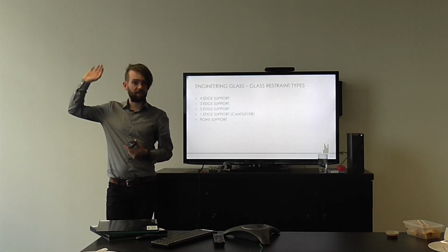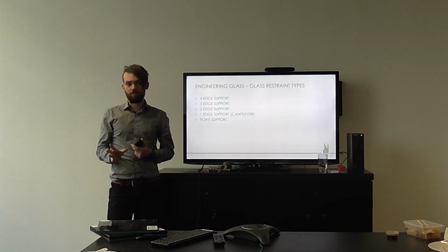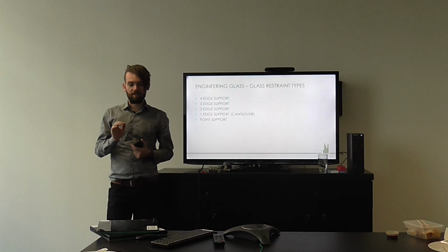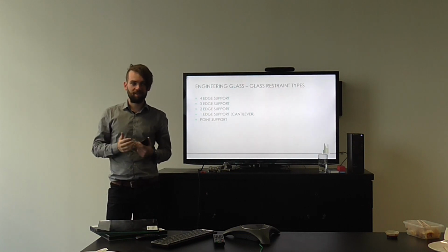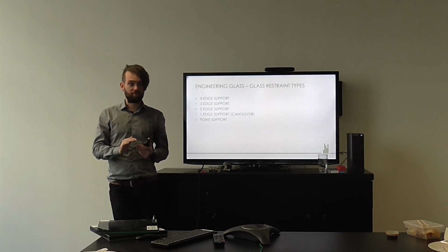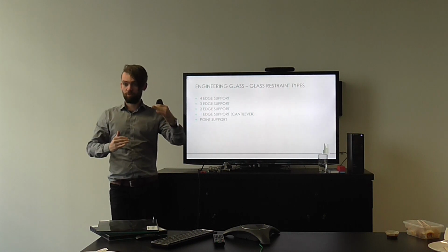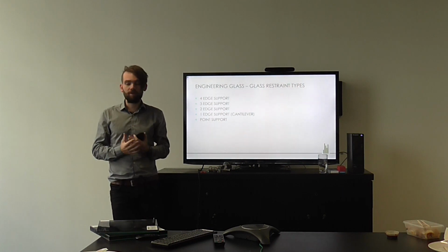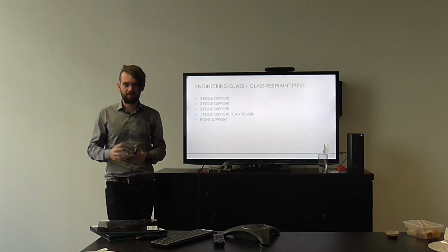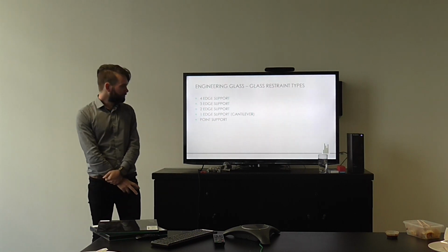monolithic toughened glass breaking and falling from a great height, in the Australian standard, the way that is actually written is that, provided that fall is greater than 5 metres, the glass needs only be heat soaked. Whereas our specification says if it's above 3 metres, you can't use it. So you're definitely right, there is a gap between what is compliance and then what we try and push, and it's just about us driving industry best practice and making sure that we're being safe and people aren't going to get hurt.